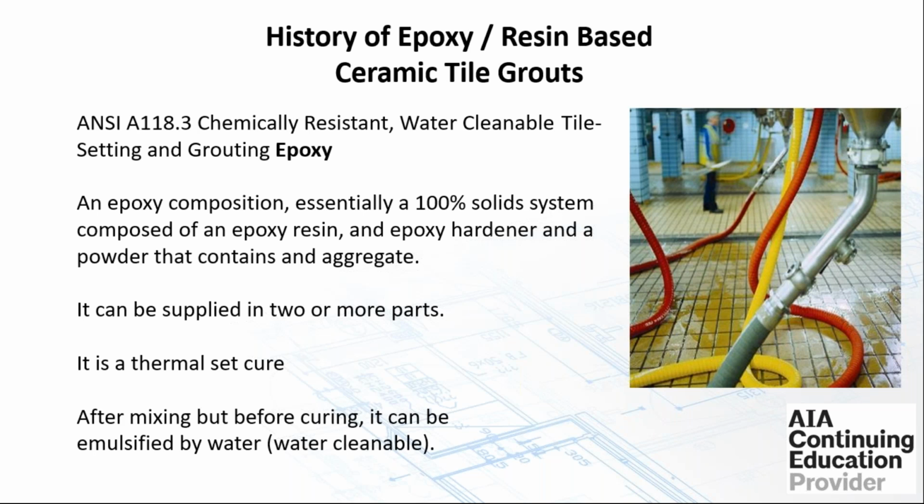A lot of times when you're talking to an installer, they'll give you different reasons for why they don't want to use the epoxy. In most cases, they're just not comfortable working with it. Maybe they had bad experiences in the past, and they don't want to go through that again. But you can find that these epoxy grouts are a lot easier to work with now than what they used to be. In some cases, because of the way the aggregate is put into it, grouting with an epoxy with a very dark grout, like a black grout, I find it easier than a cement grout.